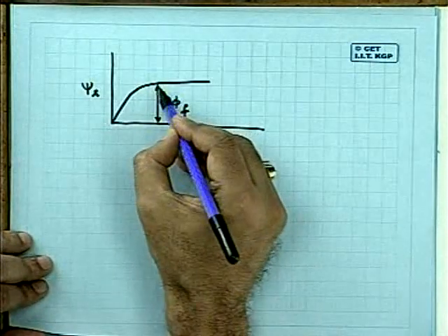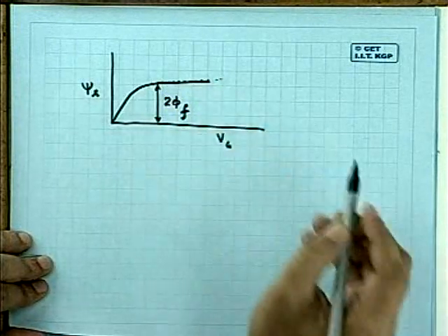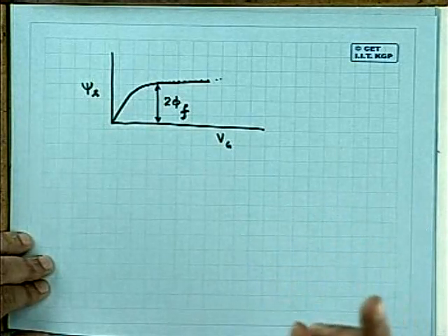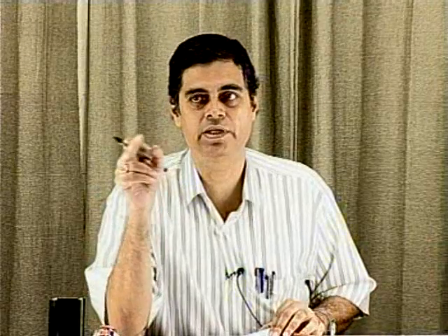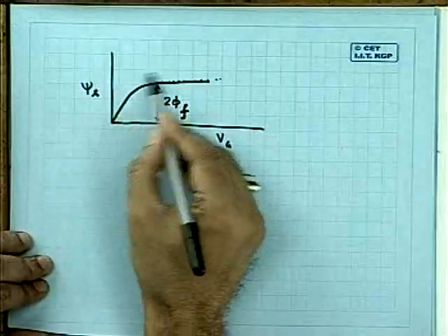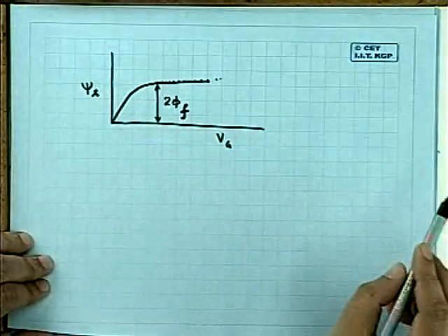And actually, remember, beyond this point, Qs increases with the surface potential following e to the power Q psi s divided by 2 Vth rule. 2 Vth, we have discussed it earlier. But it is so rapid in the linear scale that for all practical purposes, I can assume it to be constant.